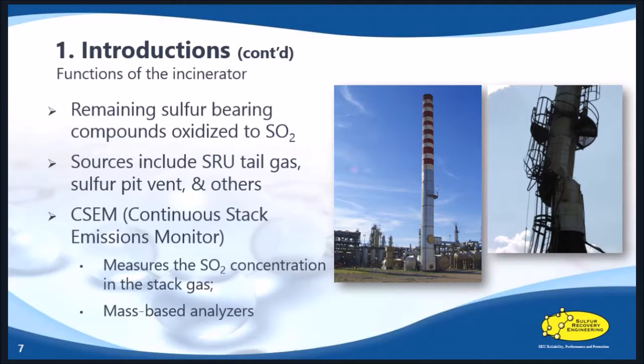The other key component at the stack is the CSEM, which stands for Continuous Stack Emission Monitor. Depending on the location of your plant and the environmental body, this instrument measures SO2 concentration in the stack exit gas, and it reports directly to the environmental body. And some stacks also have an oxygen analyzer as well. However, these oxygen analyzers many times do not perform well because of the nature of the acidic gas, and it creates sulfuric acid formation there.